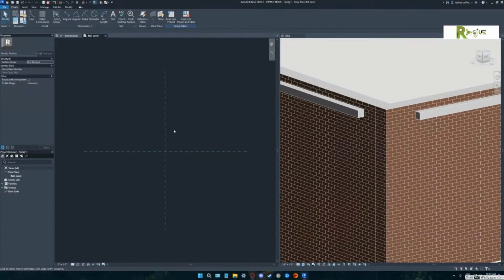So a profile is a type of family, and I think there's probably somewhere around 30 different types of families. But that's why I wanted you to be in the plan view when you opened it, so that we can see the profile in this view. And when we push it, we can see what it does in the other view. So all a profile is, is a closed shape. When you're in that profile family, which you are, all we can do is basically draw lines and put detail components in it. There's not a whole lot of choices of what we can do.